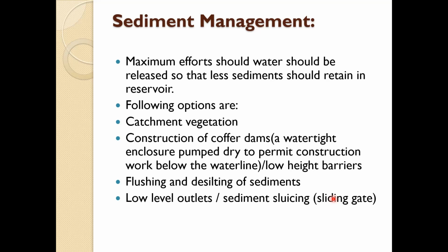Then mechanical stirring of sediments. So the deposited sediment is caught and disturbed by mechanical means so as to keep it in a moving state and thus help in pushing it towards the sluices.